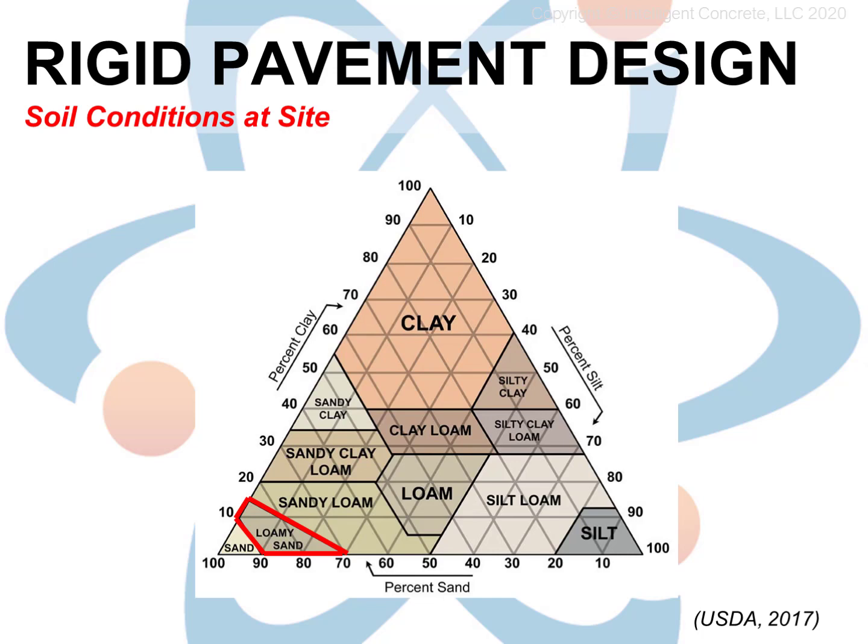In the end, the percentages all have to add up to 100%, of course, but these ranges of sand, silt, and clay result in the soil being referred to as a loamy sand, which for construction purposes would be considered a good quality soil, all other things being equal.